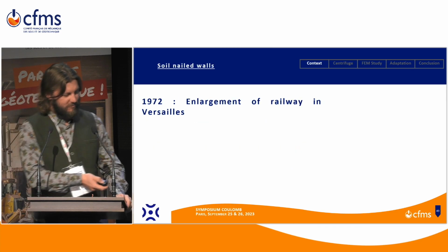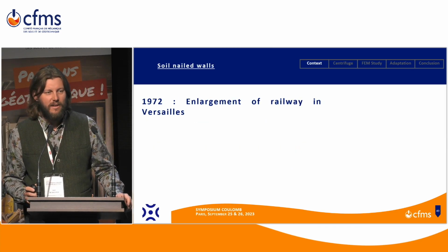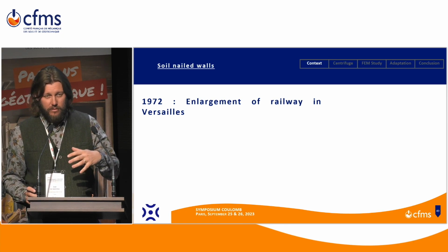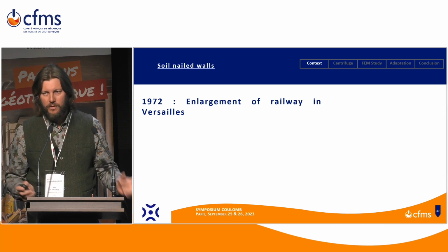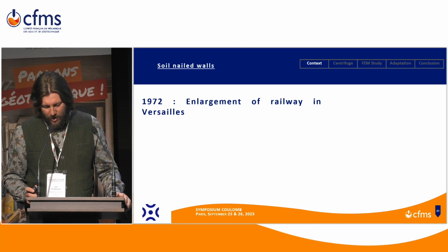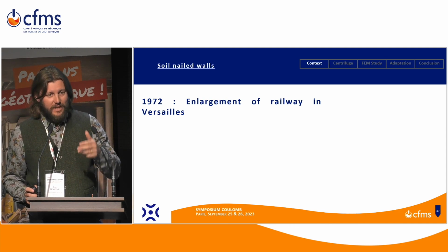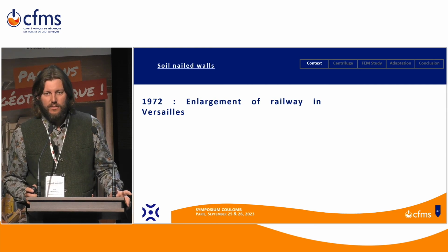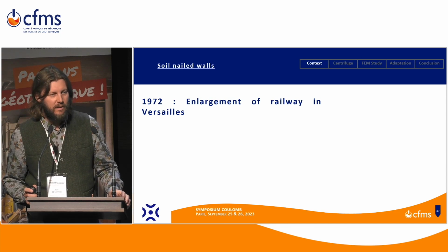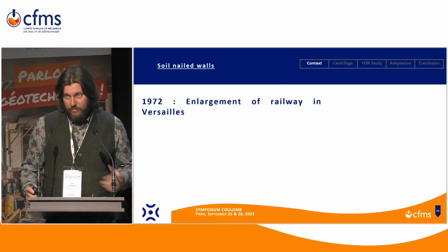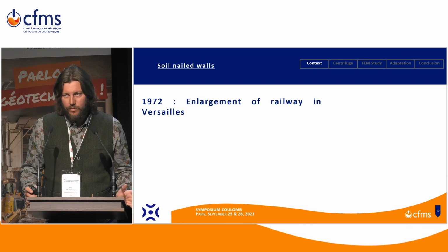So, to begin with soil nailing, I will just do a bit of history. The idea originated from the Austrian method for tunnels, which consists in rock bolting, let's say. And it was adapted to nail the soil in place. And the first example, to my knowledge, was done in 1972 in Versailles to enlarge a railway station. But then it became soon popular, and there was the need for recommendations.